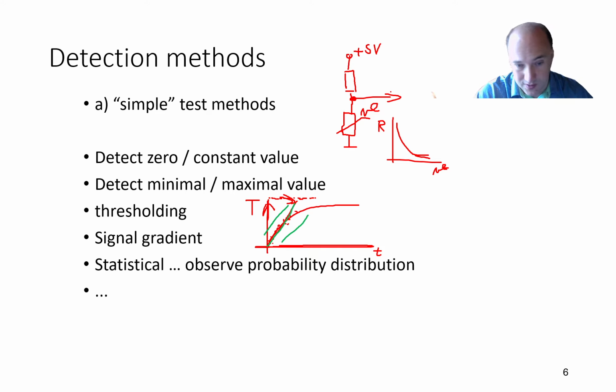And the typical outcome of this is that, let's say you measure temperature in a room, for example, so you know it's somewhere around 20 centigrade. But when this happens, when this sensor is destroyed or disconnected, you will get some reading that's something like minus 150 centigrades. So, okay, I can measure minus 150 centigrades with the thermistor. But in my application, where I measure the temperature in a room, now this is very suspicious. So this is most certainly a wrong reading.